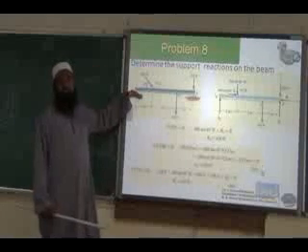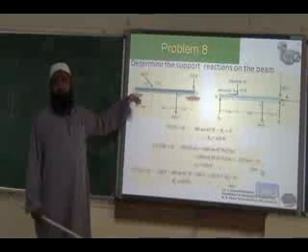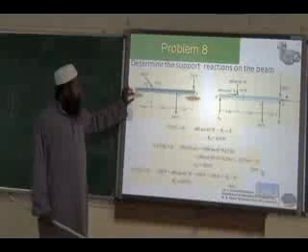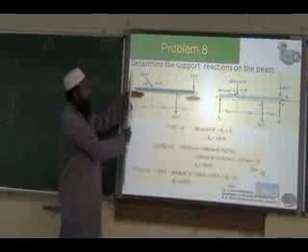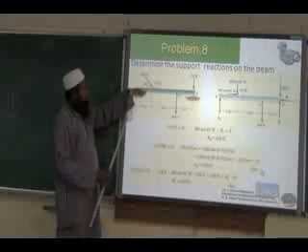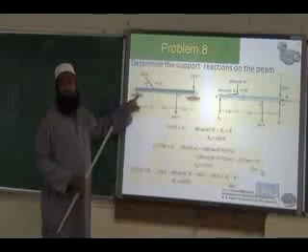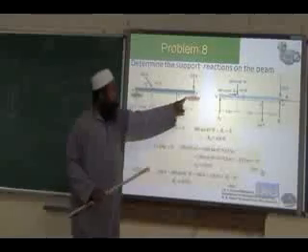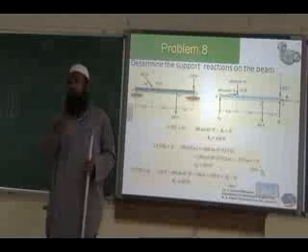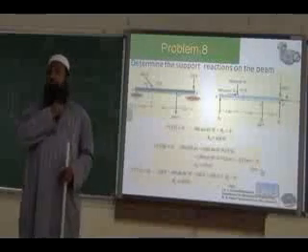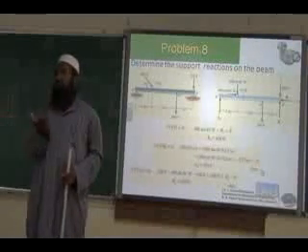It's a flat surface and it is not fixed to the support. Okay, so this end will not allow the beam to move in y direction. But it can slide, there is no bolt here. Okay, here we have a bolt. So this bolt will fix your beam on the ground, so it will not allow it to move. It will not allow you to move in x or y direction.